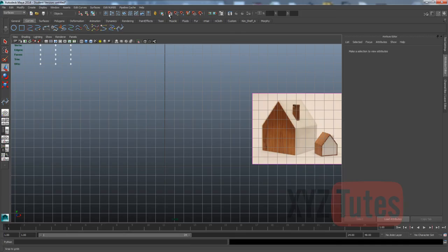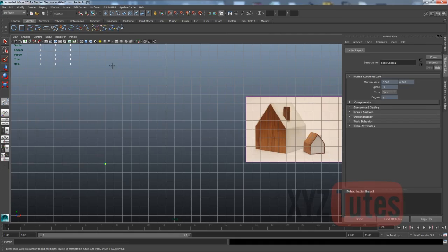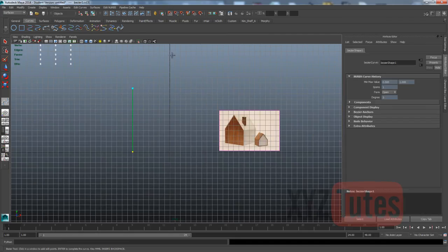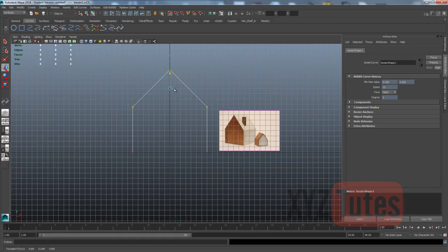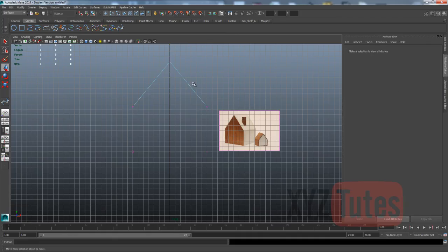So we're going to do that, and we're going to use snap to grid up here. The toggle for snap to grid is X on the keyboard. So I'm just pressing X to toggle that on and off. So here we go. We're going to create our basic shape, and I'll adjust it afterwards. I just want to make sure it's symmetrical. When you've finished clicking, I just held X, so that's snap to grid, I'll press enter. And then I'm going to just move this down. I'm not quite convinced about the shape I achieved, so I'll do some adjusting so that looks approximately right.